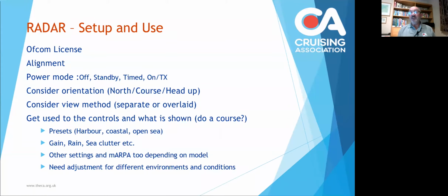Think about the power modes that are used. If you have plenty of power on board, then you don't need to worry about the standby and timed. But basically, off means it's using very, very little power. Standby means that it is ready to go once you hit the power button and the scanner actually starts to transmit and receive. Timed means perhaps that it will give a couple of sweeps every 10 minutes, for example, as a way of saving power, but still looking out for any ships. And then on is when it's actually transmitting that radar signal and therefore getting back information that you can use.